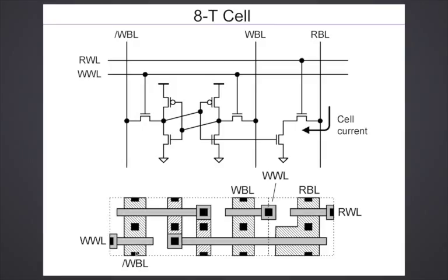The bit line is connected to the right bit line, which is connected here, goes vertically like this, right? Similarly, you have the ground for this transistor and the VDD for the PMOS transistor. If you notice out here, this ground, only half the contact is shown, because the other cell on top is reflected, a mirror image of this, so that they share the ground contact. So the area is half.